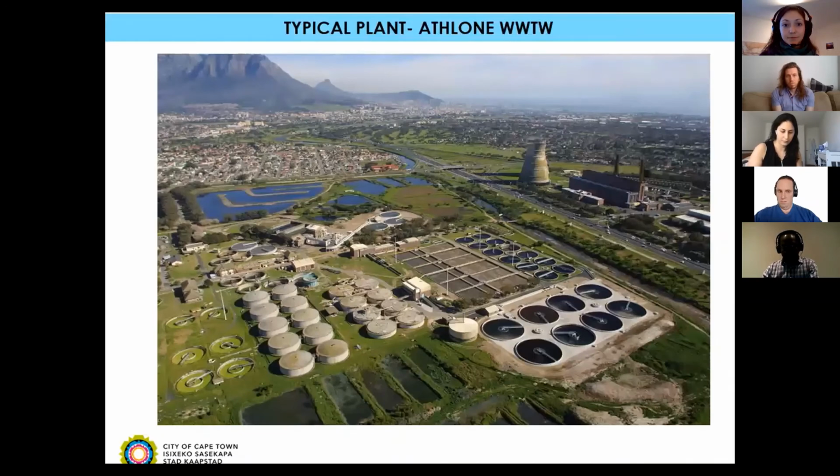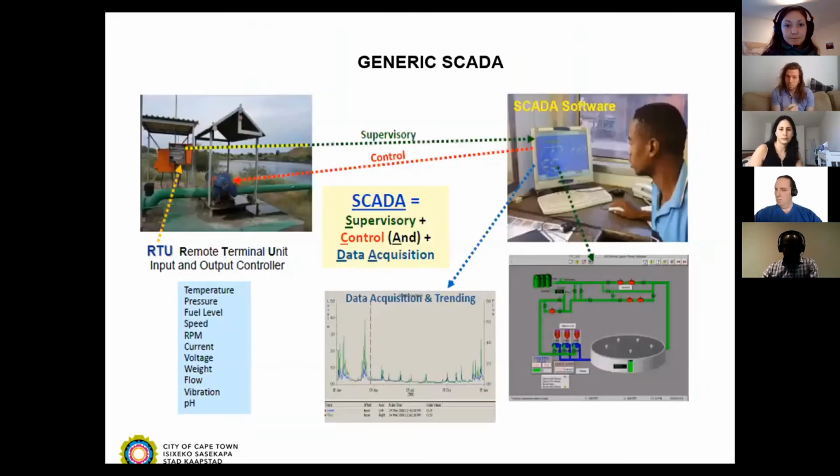Yeah, this is one of our wastewater treatment plants, Athlone treatment plant, along the major freeway N2. What I'm showing is the generic SCADA systems, and we're trying to move away from these generic SCADA systems into an OPC UA environment, which I will share later on. For example, it's an RTU sending information to a SCADA, and the SCADA is logging and trending that information.